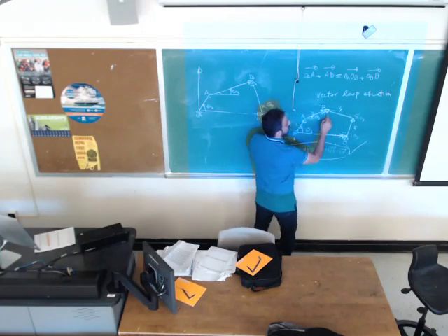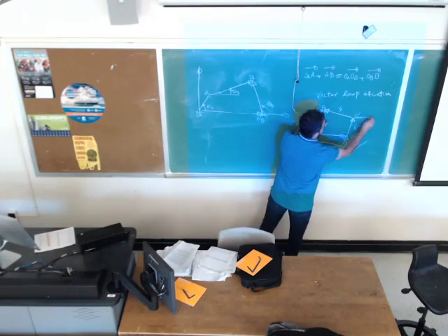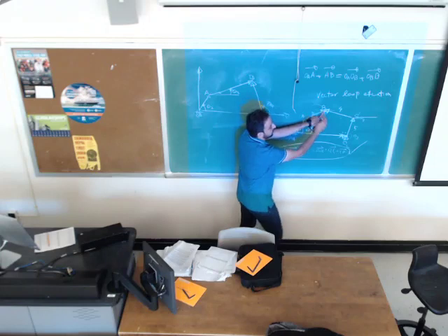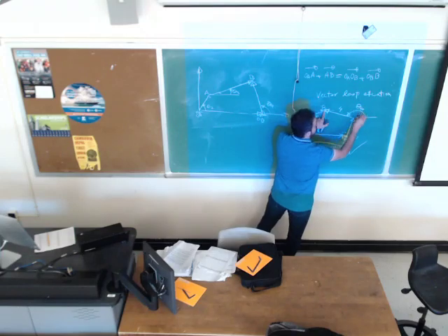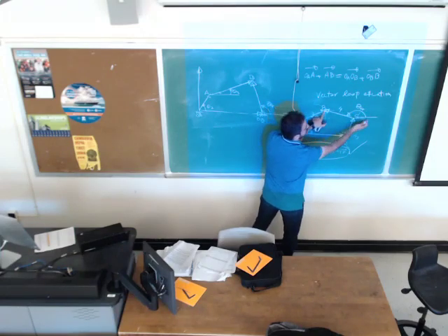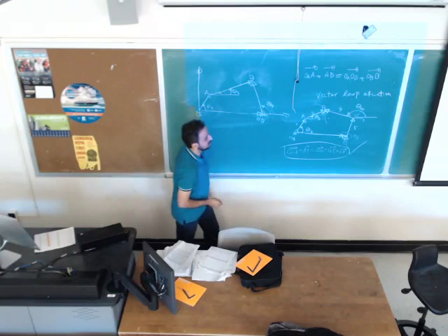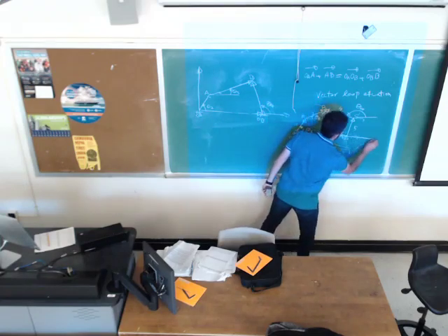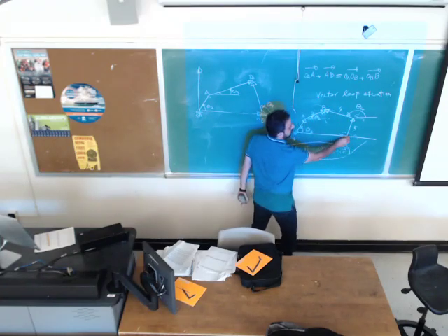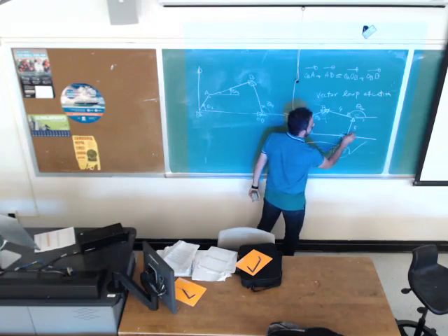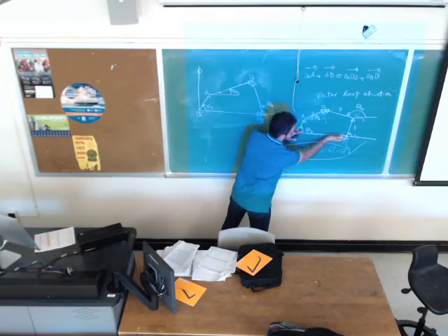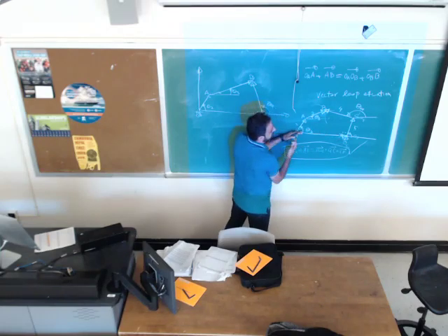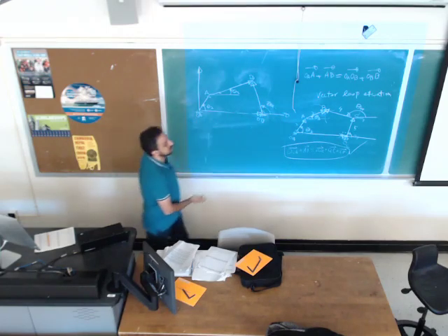Link 4, I should measure theta at point C, not point B. Draw a line parallel to the ground, measure theta 4, which represents the angle of link 4 with the ground at point C. And for link 5, since the starting point of the vector is this, I can measure this as theta 5. The ground link is going to have an angle of 0 with the ground.